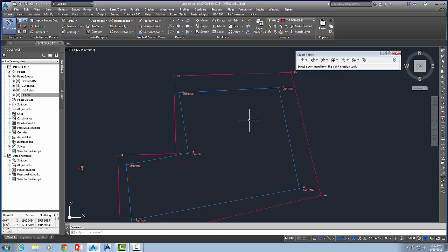The one big problem with this type of solution is that it yields two solutions typically, and so you have to pick the proper solution. And sometimes it's very obvious, and sometimes it's not. So if you're going to do a distance type of intersection, you should preferably do it with like three distances as opposed to 2.